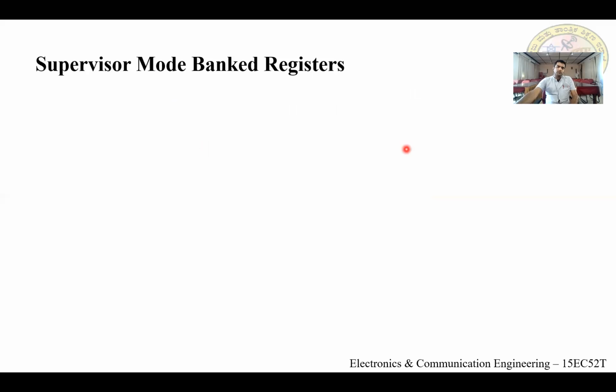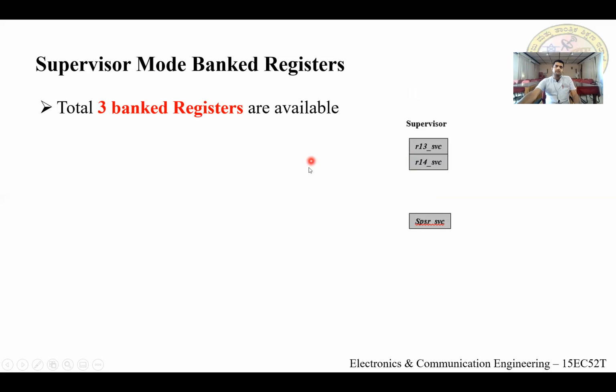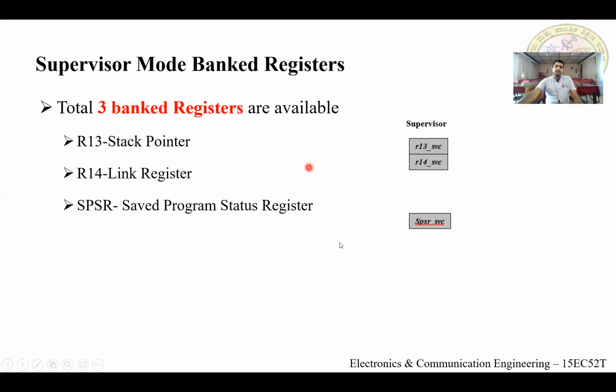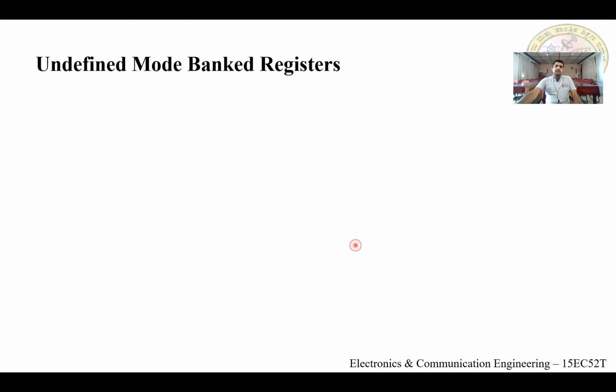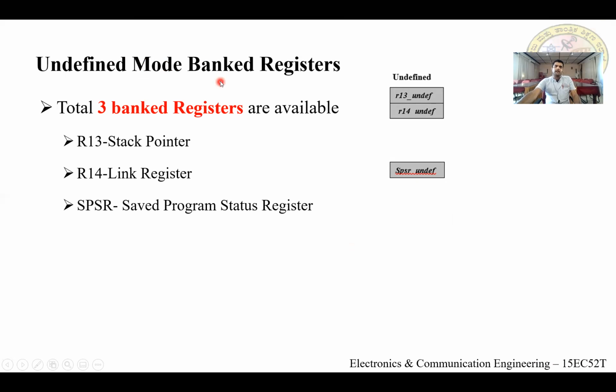In supervisor mode, there are 3 registers: R13 stack pointer, R14 link register, and SPSR. In undefined mode, again we have 3 banked registers: R13, R14, SPSR. The mnemonic for that mode is UNDEF.